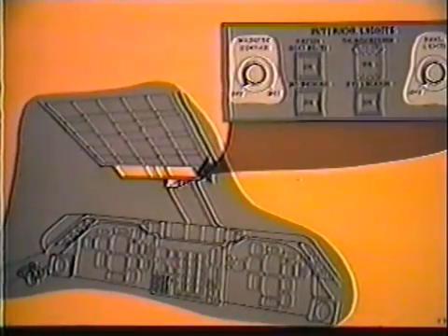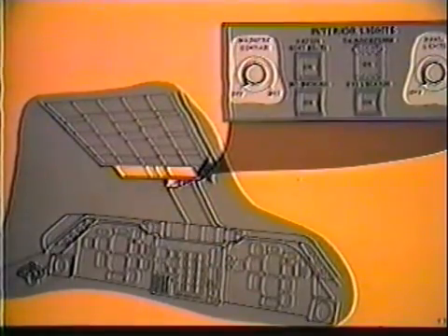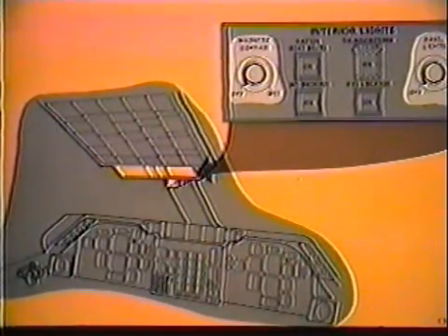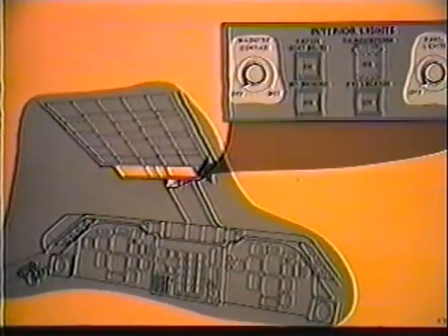The third normal lighting panel is the interior lights panel. The interior lights panel contains controls for the magnetic compass light and the eyebrow panel backlighting. This panel also contains the fasten seat belts and no smoking switches. Activation of either of these switches illuminates the corresponding cabin sign. The guarded thunderstorm switch, when latched, will bypass all dimming controls and will illuminate all lamps to full brilliance.